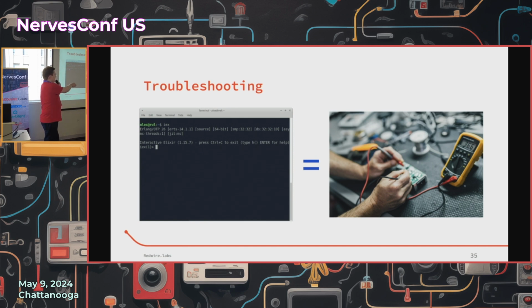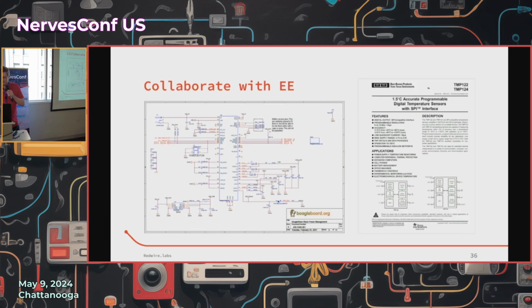when you go look at part of the circuit, say you're looking at the voltage coming into a chip, and you see 0 volts, well, that's not something you're necessarily going to be able to see from the console, ignoring Pal's awesome example of his live view thing. But this is going to show you, okay, I have a physical problem with my board. I'm not getting power to this chip, which is why I don't see that chip on the I2C bus, or why I'm not able to read and write from it. So that could be something to really look at there: understanding those other tools that are available, getting used to them, and familiarity can really help.